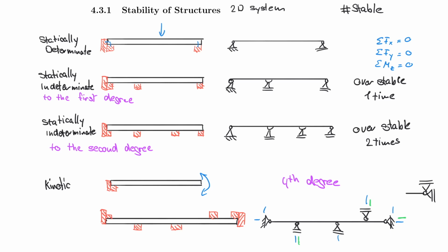And now I invite you to think about this. Why were you able to solve support reactions for systems like these? You have done this already in your homework, but why would you not be able to solve these systems? And the answer is actually on this page here right now. And of course, I'm not telling you too much if I say that this is the real reason here. So the reason you can solve these simply supported beams so far only, and not these systems below is because you have three equations, right? Or three conditions. And when you want to solve three equations, you can solve to a maximum for three unknowns. And that's exactly what you have.